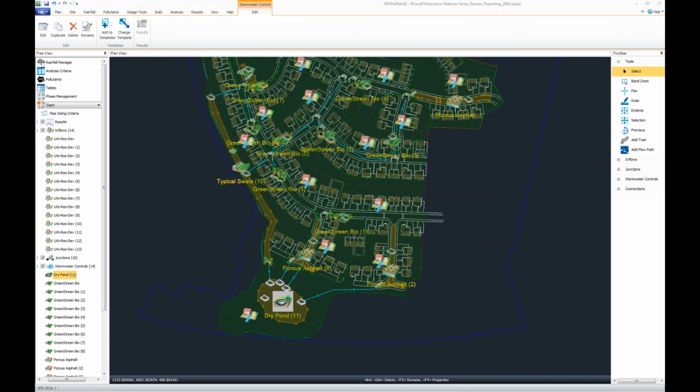And one item here is how does the tailwater, the downstream control, work? In the 2016 release, we are going to take into account when there's a higher water surface level downstream. So it's smarter than just stuffing flow into the next downstream item no matter what. We're going to stop flow based on a tailwater influence. Something we're planning for the next release is more robust tailwater control, with time varying series and whatnot. That will be coming up quite soon.